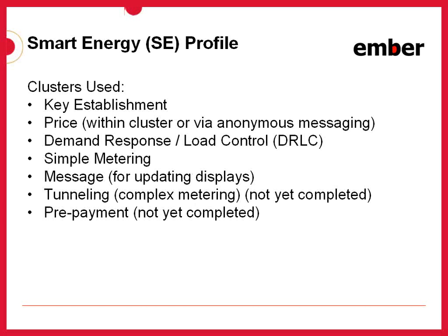We have simple metering, which is basic control of accessing the meter usage data so that you can have a display device report information about what's going on in terms of the meter usage. We have a messaging cluster for sending text messages and that sort of thing to a kind of display that I mentioned. And then forthcoming clusters include tunneling, which would be the ability to tunnel more sophisticated legacy metering protocols on top of ZigBee. So this would be something that's still being worked on, as well as prepayment for areas where customers may want to prepay for their utility service.